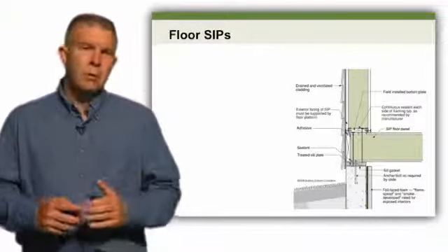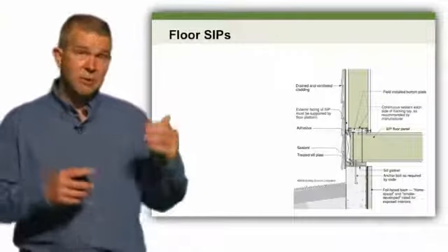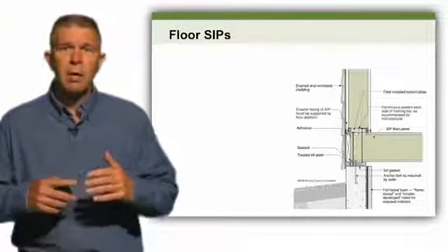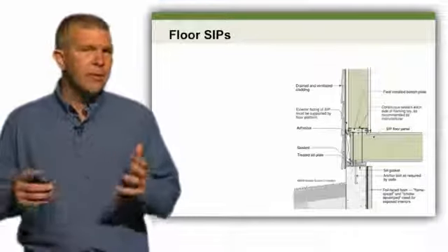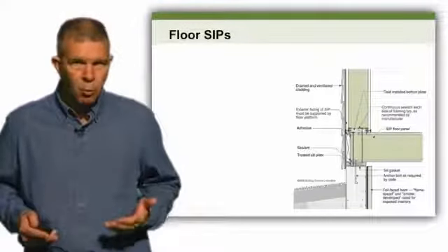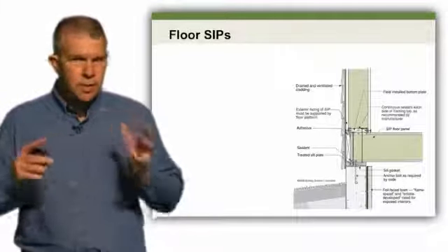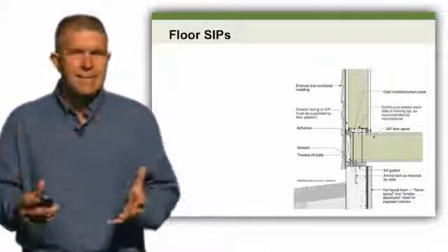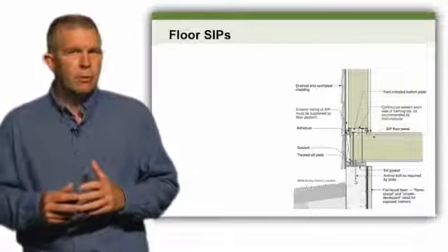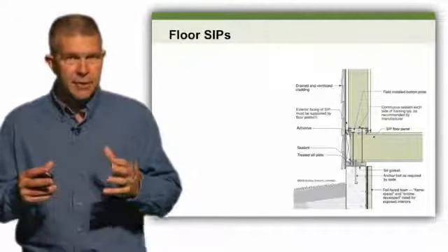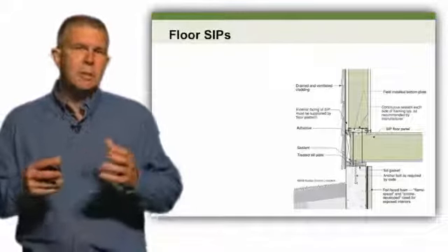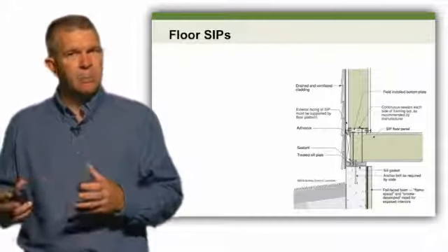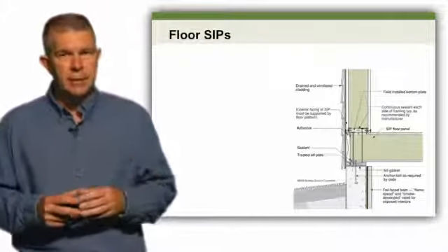All right, at this point, as you can see behind me, we're going to talk about building this house with standard connection details, starting from the ground and working our way up. It's a cursory overview of the details in the most basic sense. First and foremost, if we have floor SIPs in this particular project, let's look at this detail and see how SIPs might be incorporated into this panel package.